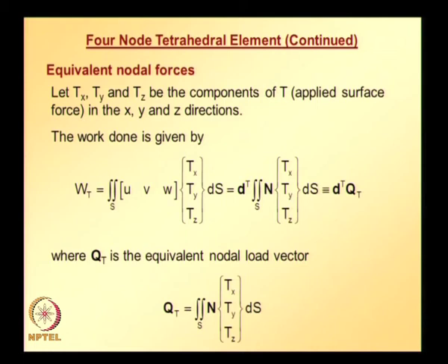To evaluate this q, integration can be performed in closed form if specified surface tractions are assumed to be constant over the element. This is for one face of the tetrahedral element, and similar integrations need to be performed separately for forces applied along different faces of the tetrahedral element.